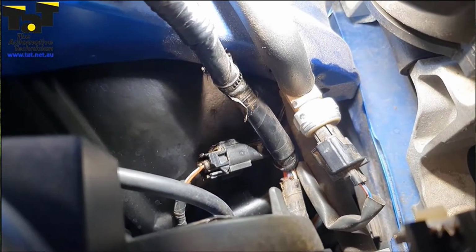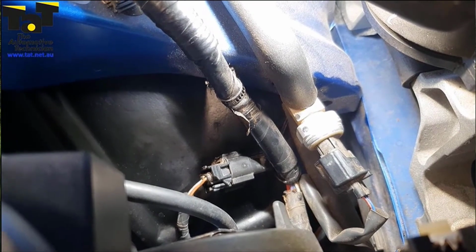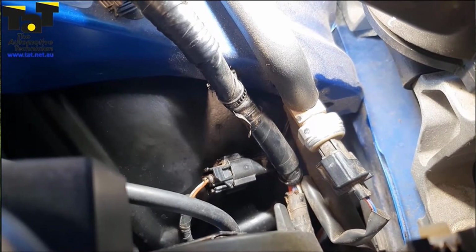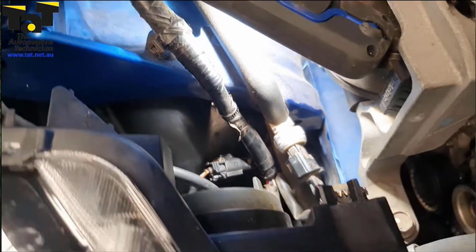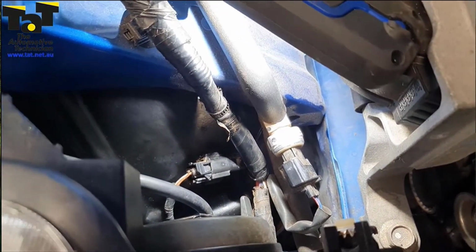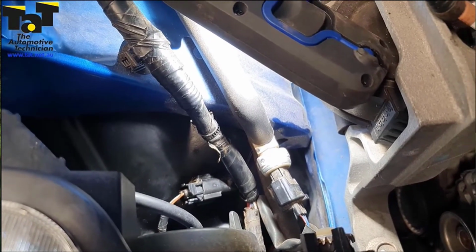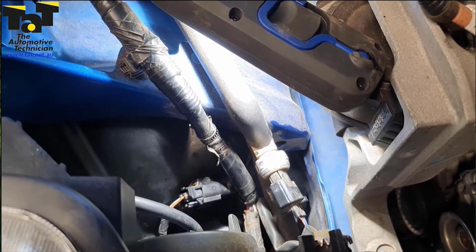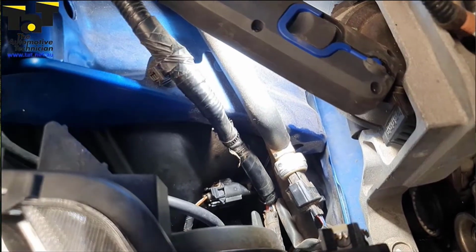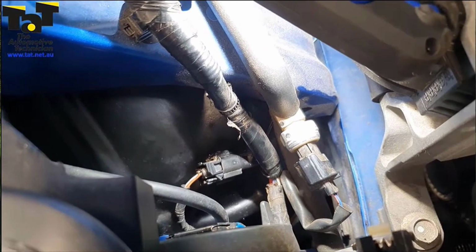What I'll do is show you what it looks like on a scope if you've never seen a magneto type active wheel speed sensor with a digital square wave instead of your normal AC type sine wave. I'll connect the scope up, put it in AC coupled mode, and we'll get the Verus on there too, and look at the live data. That's how we did it: look at the live data first. You can see we're getting no signal. Then we came down here with the wiring to confirm the integrity there, and there obviously wasn't any.